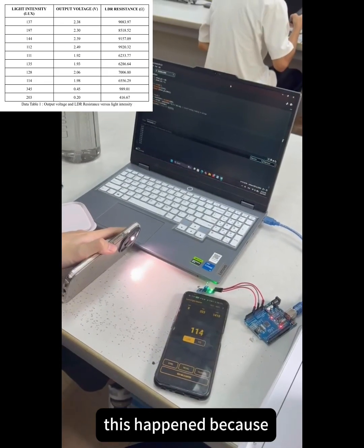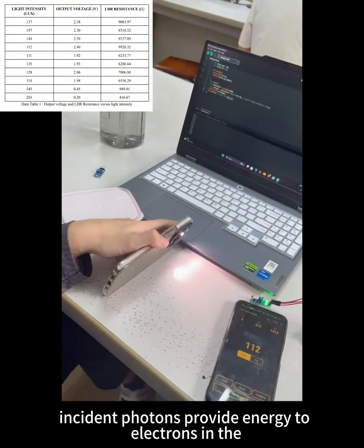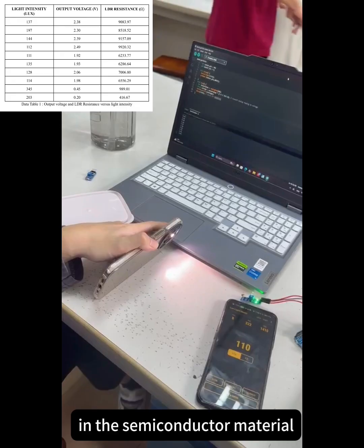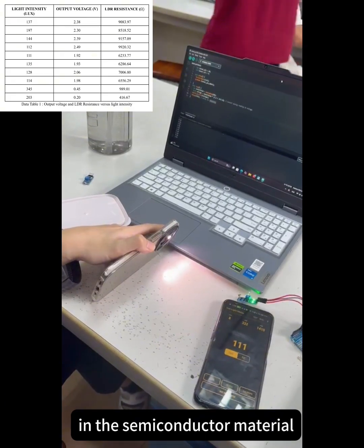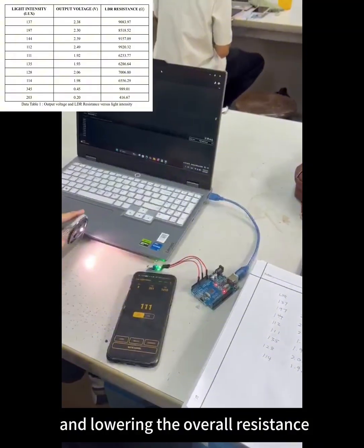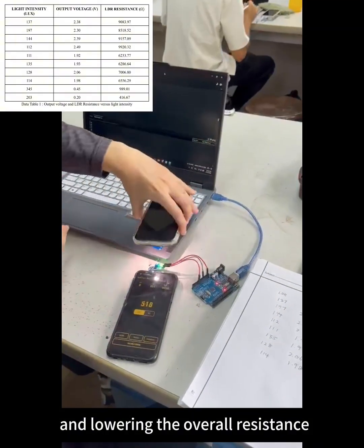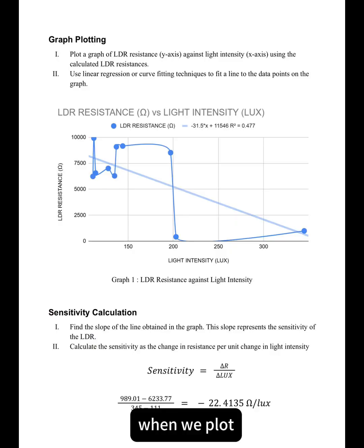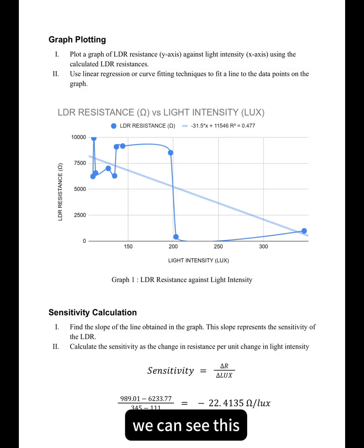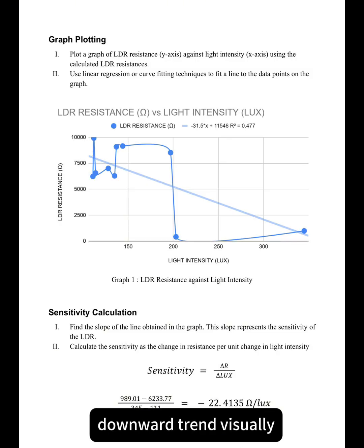This happened because incident photons provide energy to electrons in the semiconductor material, pushing them into the conduction band and lowering the overall resistance. When we plot LDR resistance against light intensity, we can see this downward trend visually.